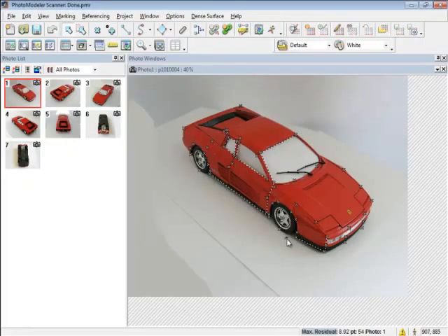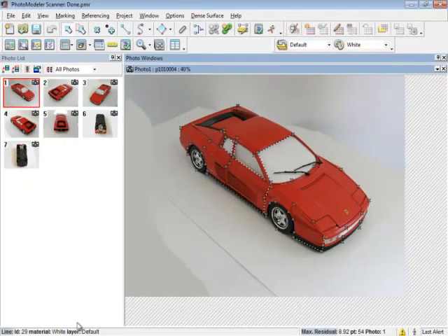The status bar at the bottom here has 4 sections. The first shows information about the currently selected object. The second shows the largest residual in the project. Clicking here gives you the option of opening the photo and selecting the mark with the largest residual. The next icon shows the status of the project based on the project review pane. You can click to open the project review pane.